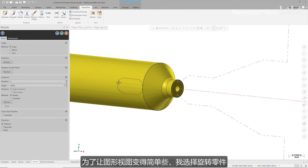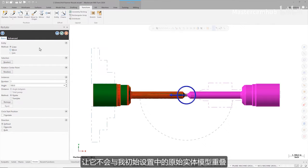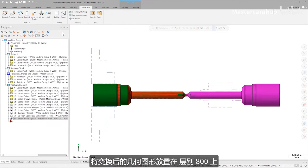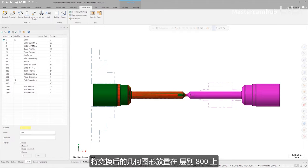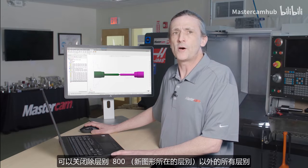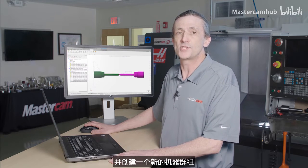To make the graphics less cluttered, I've chosen to rotate the part so it doesn't overlap the original solid model from my first setup. On the Advanced tab, I'm going to enable new attributes and enter 800 so my transform geometry is placed on level 800. Now that my geometry has been rotated, I can turn off all the levels except for level 800, where my new geometry is located, and add a new machine group.